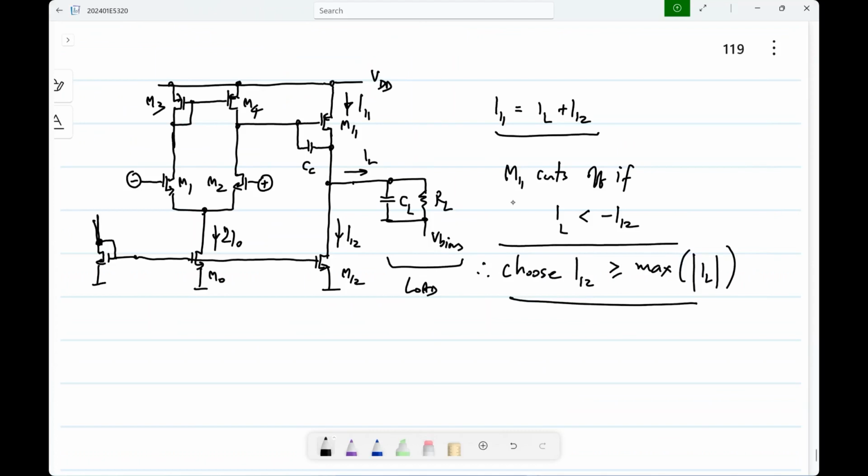So this type of biasing, this is called class A biasing. That is, you choose your bias current so that it works for all the conditions, and the same bias current is there even for zero signal. Okay. So essentially the bias current is not dependent on the signal. This works very well as far as the transfer function and so on are concerned. Only disadvantage is its power inefficiency. It's very inefficient. Okay.